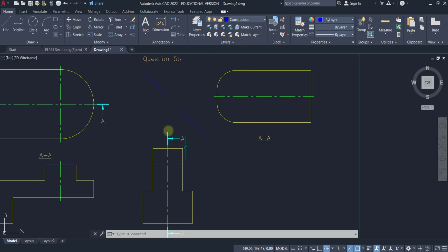Go to construction, line on the top, track from the plan view. I notice this is my extreme top and extreme left of the item. This is drawn in third angle projection. The mitre line is drawn upwards, like hands being raised. So this is third angle projection. I also know that this is going to be my extreme bottom position of the model. So if I were to draw my box, this is going to be my boundary.